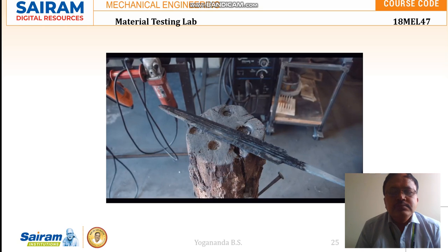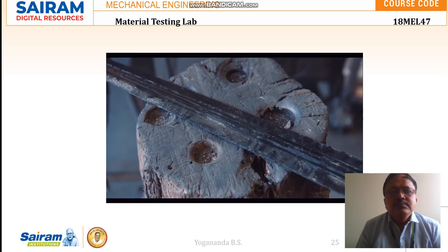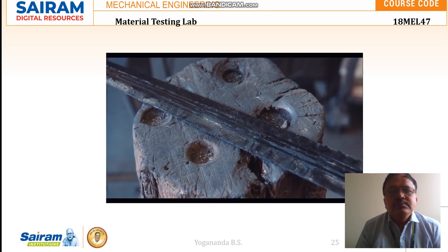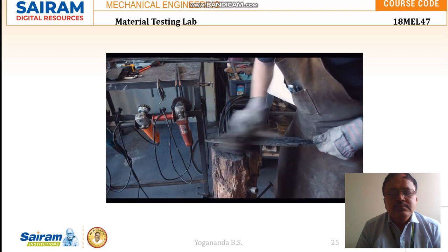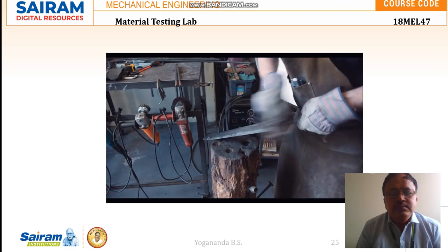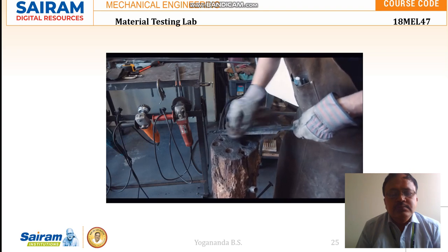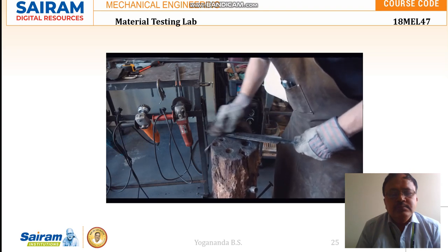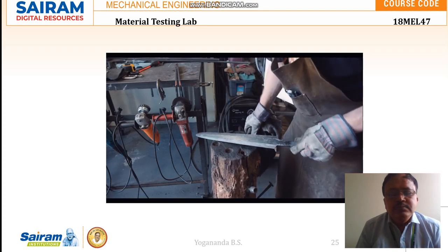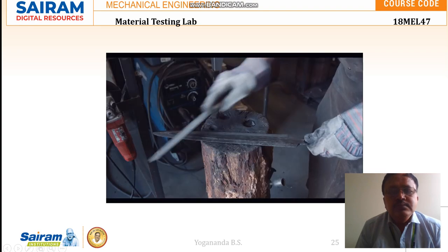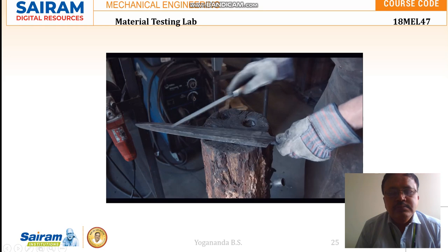If the blade has been ground unevenly, heated unevenly, or quenched unevenly, it may develop a warp and as a result may no longer be straight. However, I will show you a trick that you can use during tempering to straighten the blade. Before we go there, let's quickly check the hardness with a file. On the hard part of the blade, the file will skid, and on the unhardened parts it will bite. In this particular case, I think the blade could have been harder and I should have requenched it. However, if you listen to the noise the file is making, you will hear that it somewhat skids on the blade but bites on the tang.